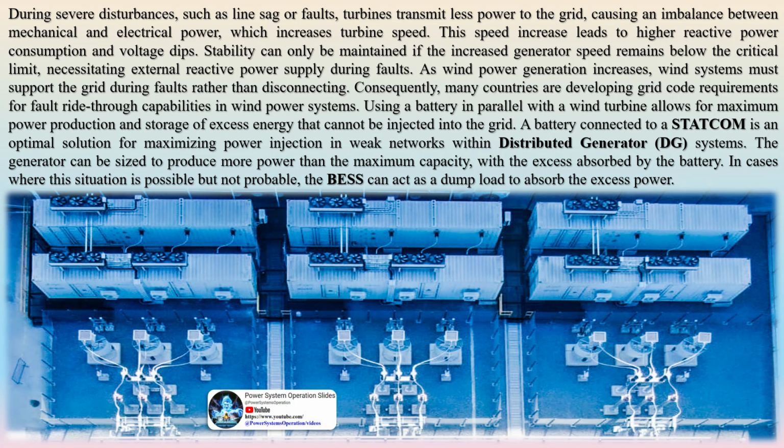Due to the intermittent nature of wind, the active power generated by wind power generators fluctuates, which in turn causes fluctuations in the reactive power absorbed by the wind power generator unit. After a disturbance, low-frequency oscillations in the AC system can be damped by injecting or absorbing real or reactive power. In some cases, the reactive power injected into the system depends on the STATCOM terminal voltage, while the ESS adjusts according to variations in real power flow.